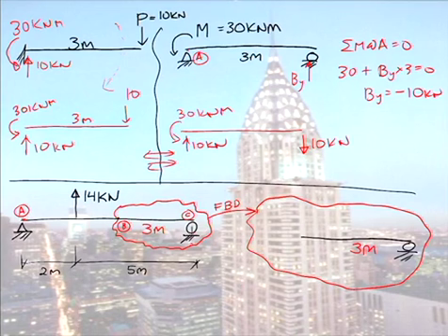Downwards. And it actually has a value when you do take moments. So you would say 2 times 14, take away this force times 7. You would get a reaction of 10 here and a downwards reaction of 4 kilonewton here.